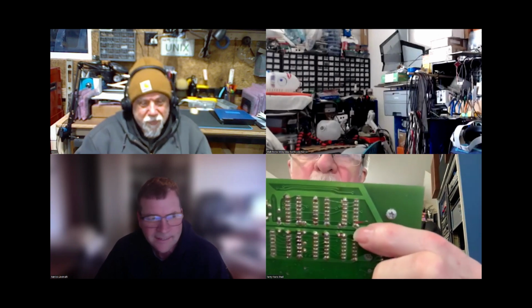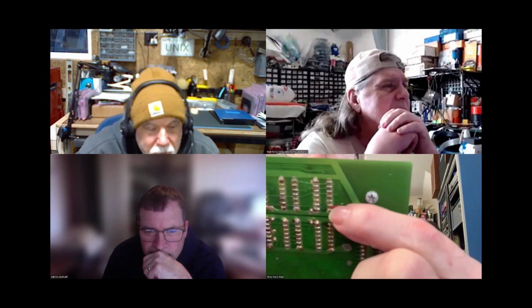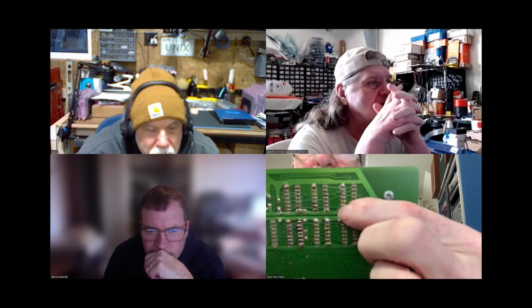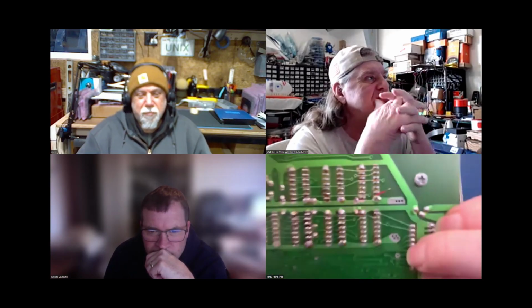Can you see this little red wire here? That was going across and shorting to this pin, I think. And it's ground. So it was grounding this pin, and nothing was working when that was connected. You wonder what possesses people to do some of these little bodges and then not realize that they made it worse. Well, maybe it was a jumper to disable stuff for the front panel, because this board may not have been in a front panel machine.